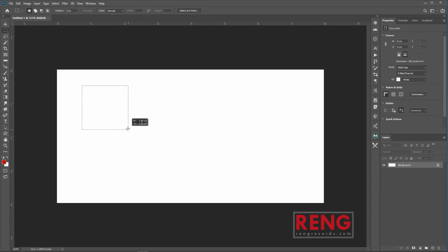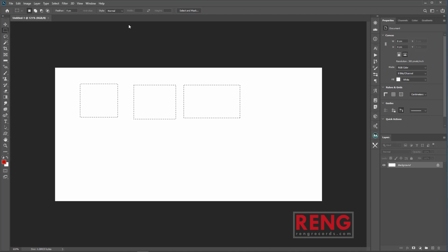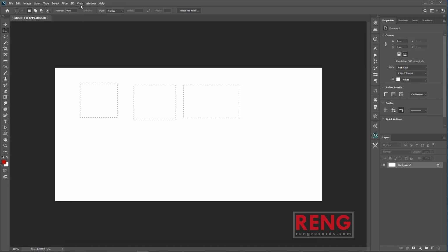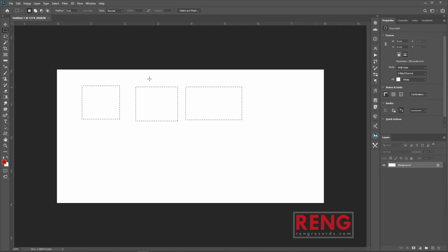Number 4. You can select the ruler tool from the toolbar at the top of the view page, or you can find it by the Ctrl+R key. After activating the ruler tool, you can use this tool in several ways. The first method is to move the mouse on the vertical and horizontal lines that are marked with the red box in the image above. Drag and place the desired line anywhere.